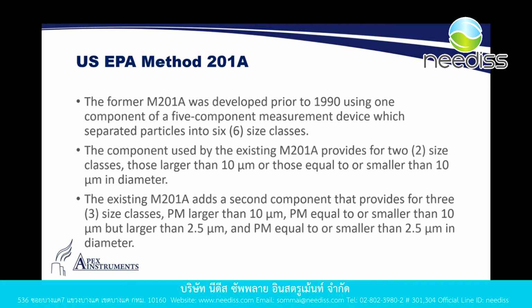And hence the cyclone, the PM cyclone that we use today for Method 201 was created. And what is good about that, as I said, is you can test a source, come back in 6 months and test it again, and use the results from both of those tests to make comparable results. So now you can see if there's improvements or no improvements in that particular source by comparing the results of these tests.